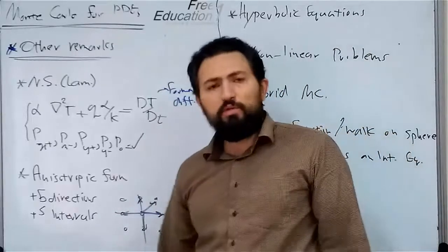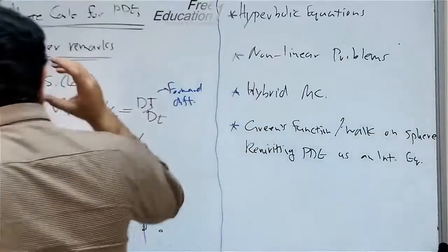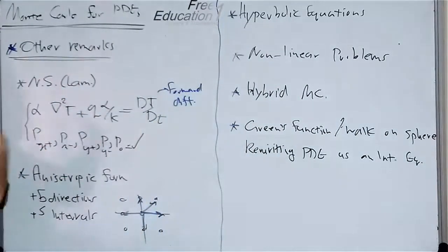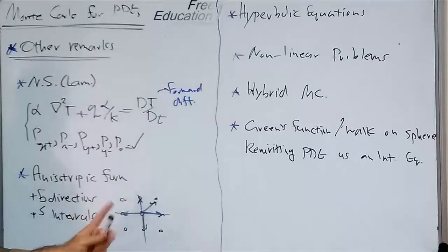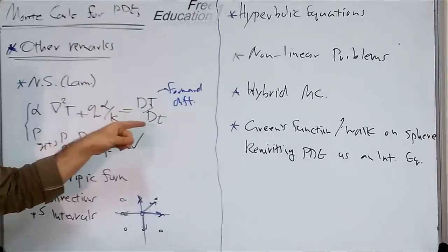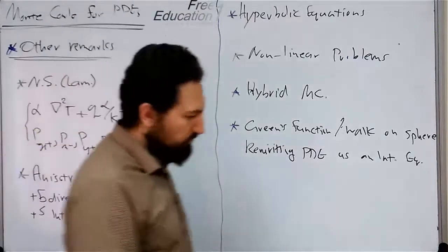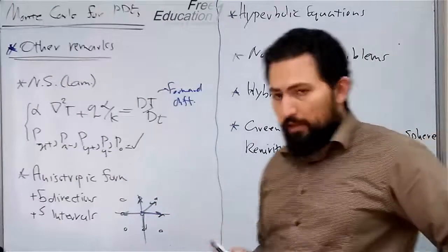Then you can continue. So the difference between the Monte Carlo method for the energy equation for a fluid and for a solid body is the different probability coefficients. In the final discretized equation, you can discretize the advective terms inside the material derivative using the forward difference.